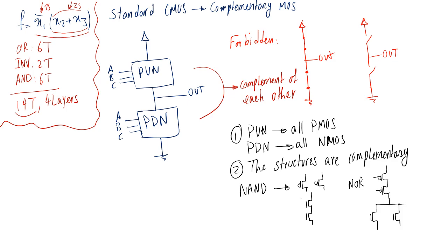And if I have the vice versa, it's going to be the opposite. Okay. And then there is a rule number three, which is not really a rule. It's more of an observation that we can make by looking at the circuits that we have had up to now. From the beginning of the second part of this course, when we started talking about digital logic design, we saw that a series combination of two things, like for example, two NMOS transistors, kind of implies ANDing, right?